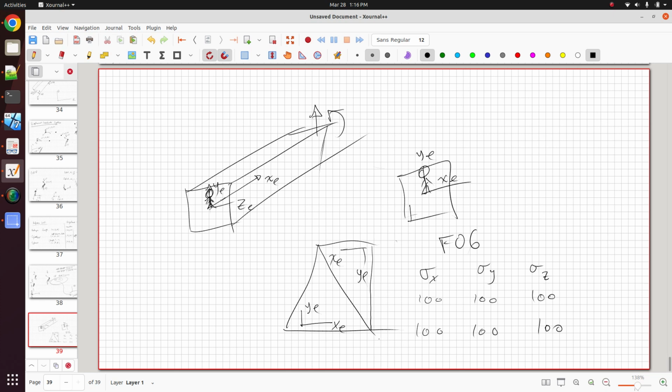So you look at one stress, maybe positive 100, and the adjacent element is negative 100, and you might ask, okay, why? To me, all the stresses should be going in the y direction. But in the F06, I'm getting different signs even though the elements are right next to each other. This is because you're looking at the results from this observer for each element.